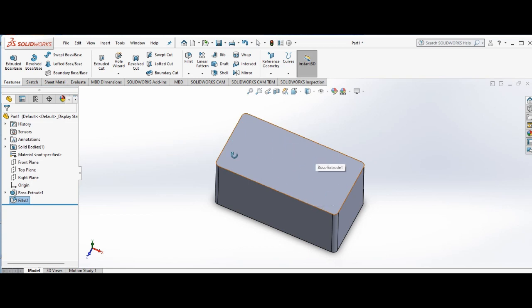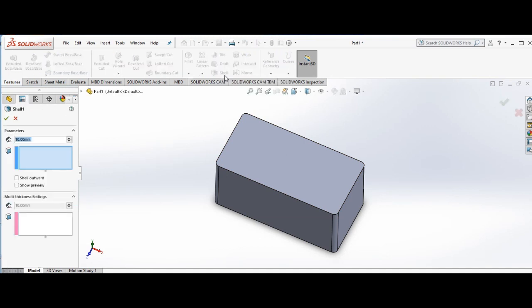So that's that. Now the next thing I want to do, I want to cut inside this rectangle because it's a solid shape now. That's why it's called SolidWorks. Now to cut into this shape, I can come directly and click this called shell. If I click shell, then I come to here, this place. The shell here is kind of 10 mm. If I click this object here, you see the display 10 mm.